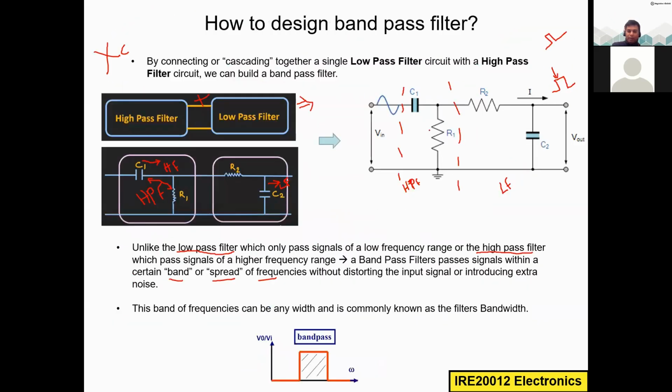So here we have the low pass filter, right? Here you have R2 and C2. Depending upon this R2 and C2, this cutoff frequency will vary. For example, here FL is equal to 1 divided by 2 pi RC, right? That is the general formula for the cutoff frequency. So here it is R2 C2.